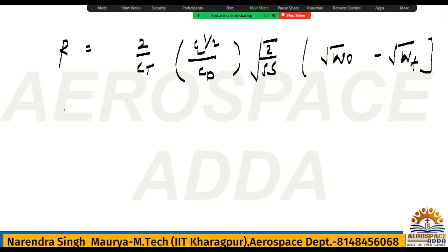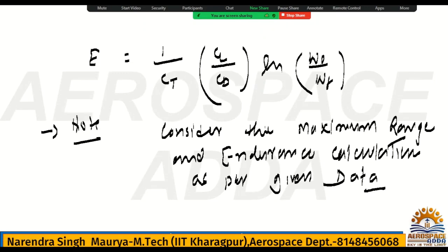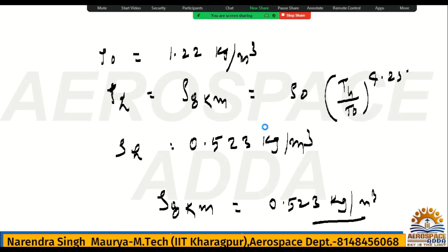How to calculate final? If I write final, otherwise you may get confused, because fuel and final students may get confused. What is the final? Final is nothing but initial weight W naught minus the amount of fuel you have burned. If you remove that, then you will get the final WF.